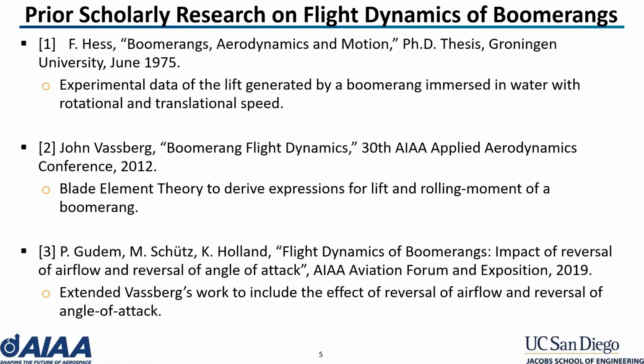I will now provide a quick overview of recent prior work on the aerodynamics of boomerangs. In the 1970s, Felix Hess did an extensive study on the aerodynamics of boomerangs and developed the equations to numerically solve for the flight characteristics of boomerangs. He collected experimental data of the lift generated by a boomerang immersed in water with various rotational and translational speeds.